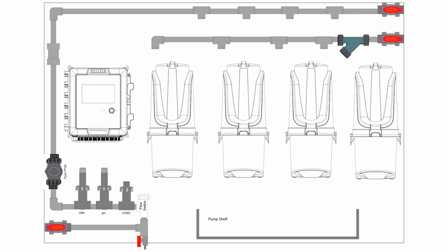So if you're feeding a product at 100 parts per million as a liquid, typically the PTSA is 100 parts per billion. So it's formulated to correlate 1-to-1, part per million to part per billion. In solids, it's 4 parts per billion per part per million of product. So it's a 4-to-1 ratio.